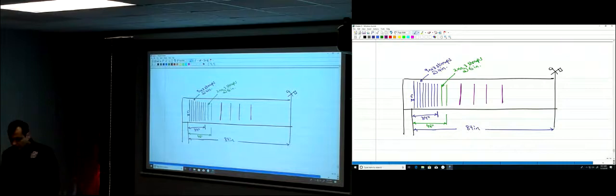Okay? So here, we said this is 82, right? So you can provide those stirrups here, okay? This is number 9, 45, so 91. So here those are 4, okay? This is just right to the middle of the beam. 4, number 3, U-shaped stirrups at 9 inches.